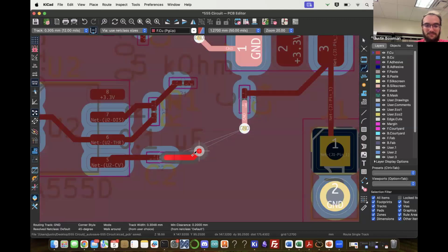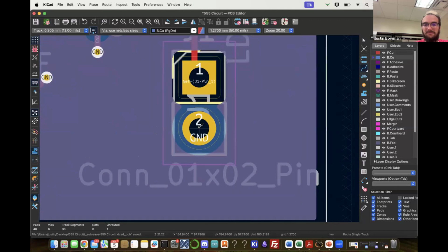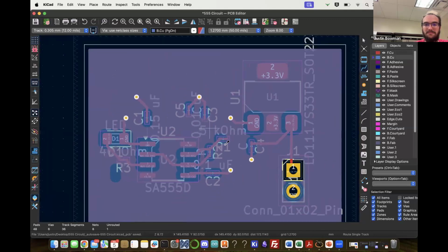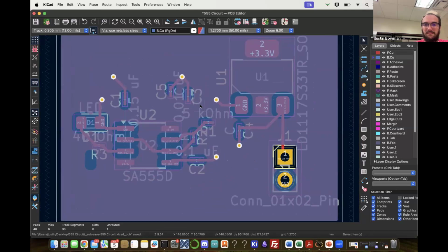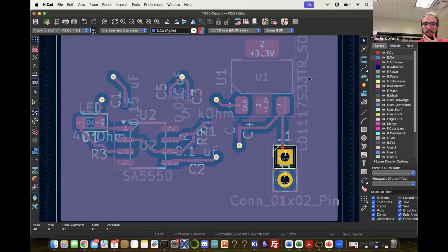That's what I have found to work, and you don't have to worry about wires or anything like that. For most projects, even this one, you can get away with single-sided, maybe put a couple of jumpers, or just put a wire instead. Just put a pin through it and solder on both sides. That's kind of it.